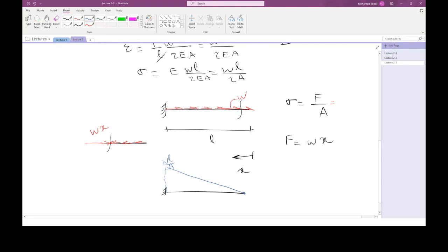Now, if you look into the stress we have from the finite element method, I'm just going to highlight that. This is WL over 2A. See, this is constant, WL over 2A. And if you look into this constant stress, you'll see that it is actually hugely overestimating the stress at the tip. Based on the finite element method, you are getting a huge value for the stress, compared to 0, this is a very large number. Whereas at the support, where you have the maximum amount of stress, where you actually have the extreme stress, you are underestimating that